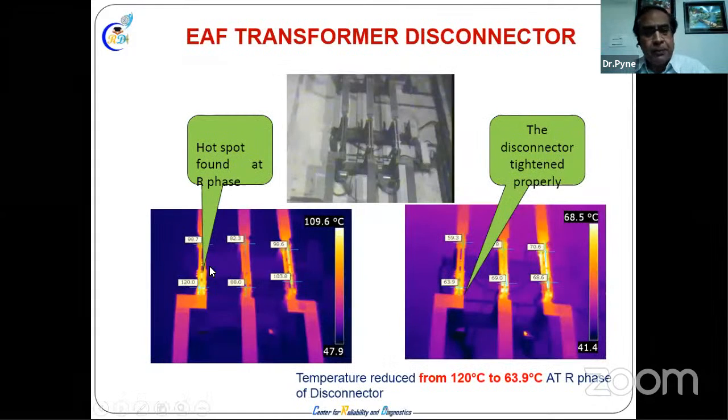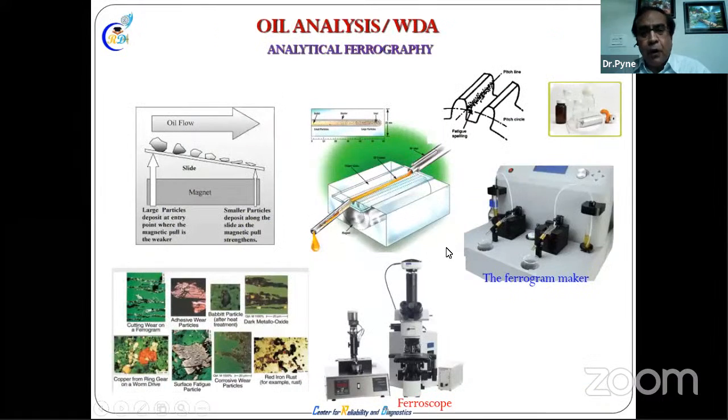Transformer, you see the hotspot here and it was disconnected. After that, this is the original picture and this is the thermal image. Okay, transformer. Oil analysis is ferrography.